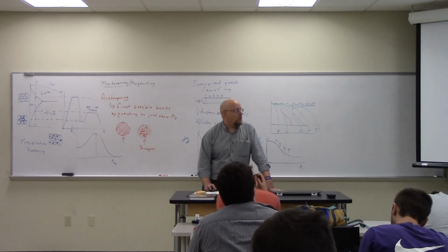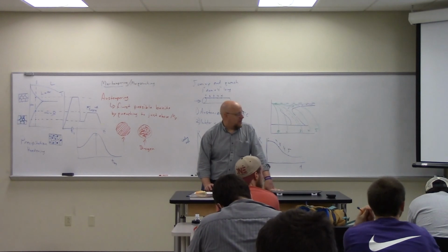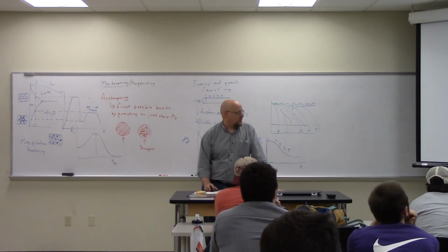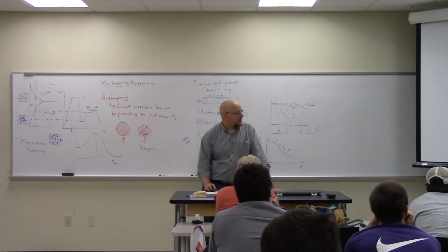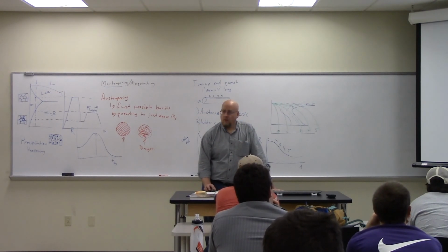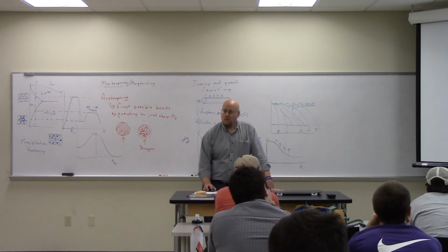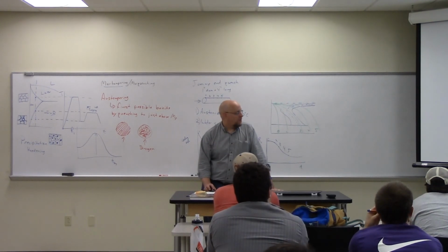So you realize the only way to get bainite from these curves is to quench rapidly, like 1 second, down to a temperature just above M sub S, so like 250. And then allow the material to cool over a long period of time. Right? The only way to get bainite is to quench past the knee to a temperature and then let it cool at that temperature. If you go right at the knee, that's still kind of coarse. Right, if you go right through the knee, you're going to get fine pearlite right at the knee.